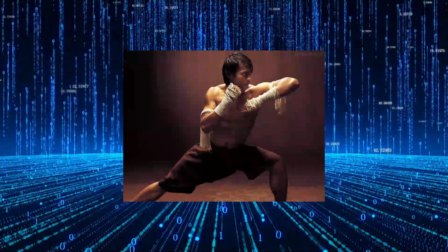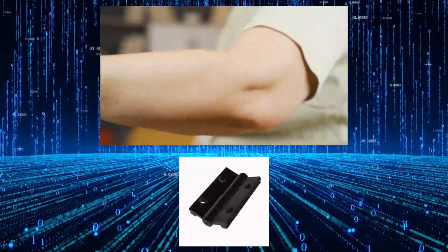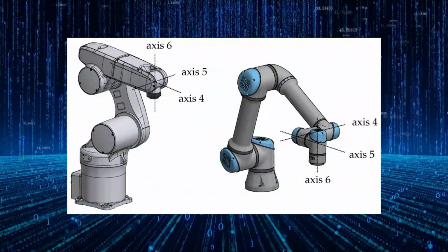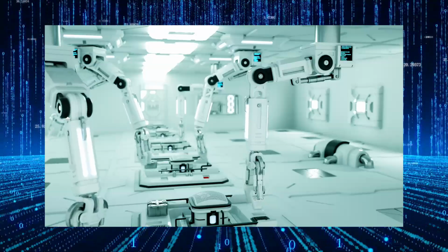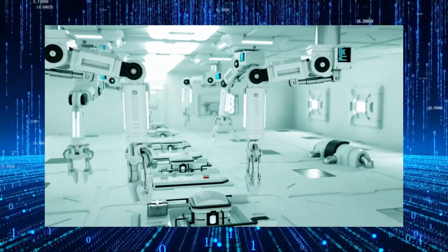The elbow is the 3rd joint in the kinematic chain and allows hinge-like movements between the upper arm and the forearm. The wrist is often given the most dexterity in robotic arms due to the need for more dexterity in industrial applications, where it helps position the end effector for precise interaction with the environment.